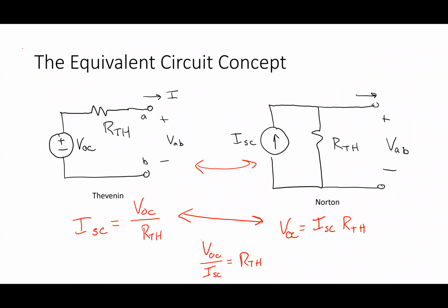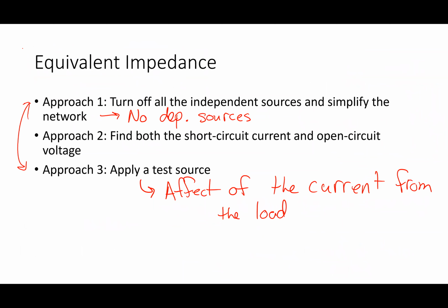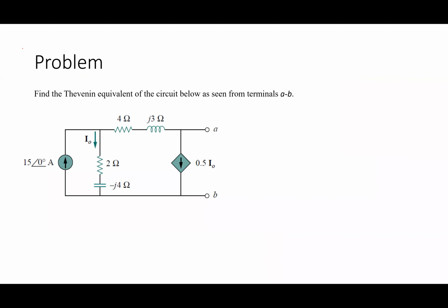First of all, one of the questions that people ask a lot: if I have a dependent source, there are 4 kinds of them. We're going to start on some of those today because this is where it gets interesting. So this one here is, let's say, A times Vx, and Vx is some other voltage somewhere in a circuit. What kind of dependent source is this one right here?